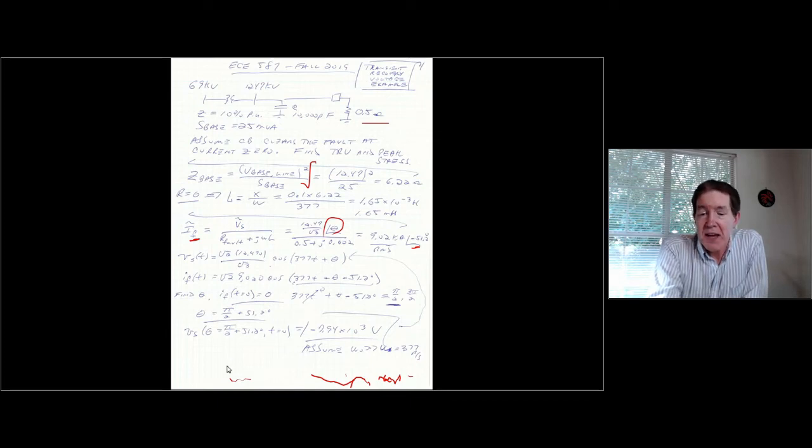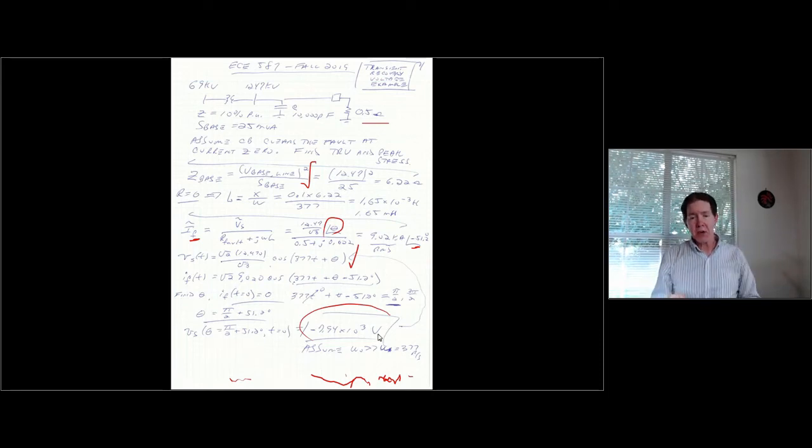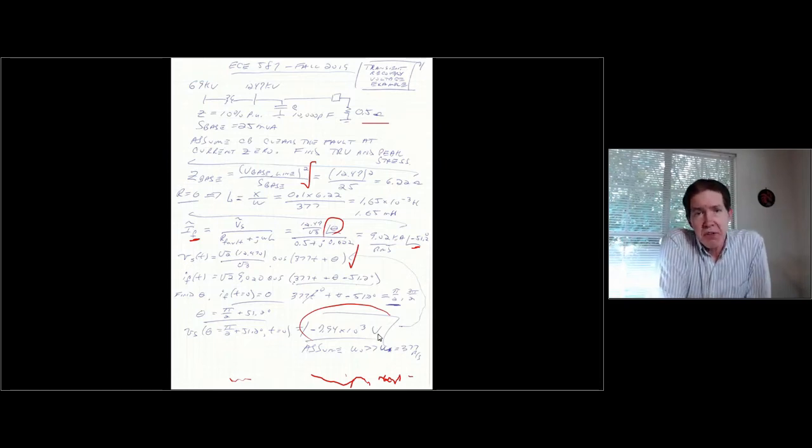degrees. And if I make that substitution into the expression for this voltage, what I'm going to see is that the voltage, when I have a 0 crossing of the current, is now going to be minus 7,940, or minus 7.94 kilovolts, right? So it's not going to be the peak voltage anymore. It's actually going to be a lesser value, and I had to do this because I was modeling a fault resistance, which changed the relationship between the source voltage and the fault current.